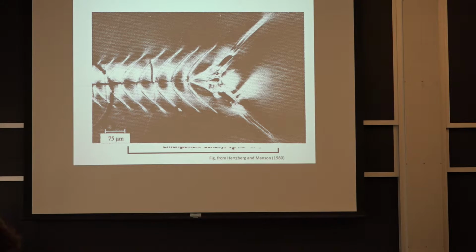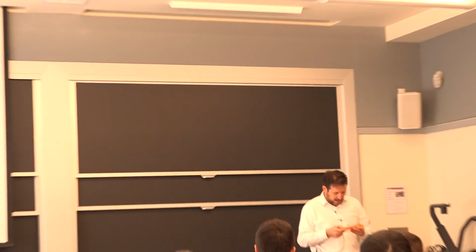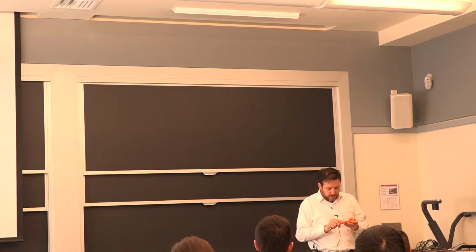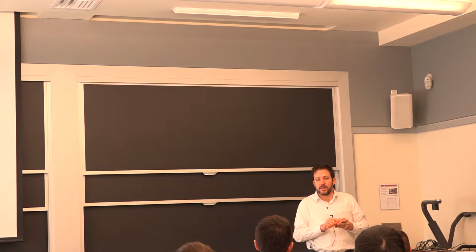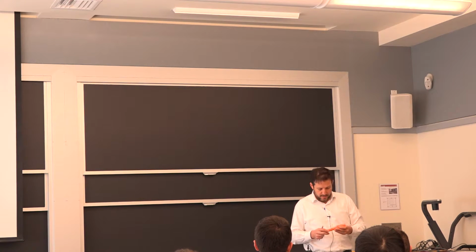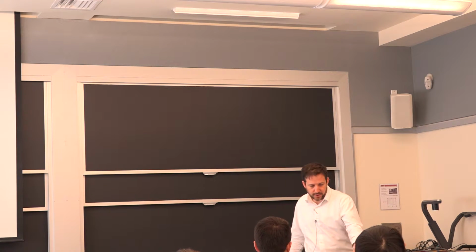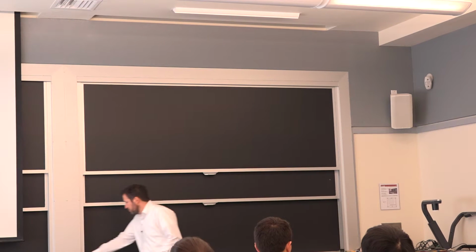So I do have a pipe sample here that I want to circulate around. It's cut in half, and you'll see one side is a clean cut that we did with a blade. The other side has a bunch of very slow cracks that started in service and grew all the way through the wall thickness before it failed. So I'll circulate it, and I'll sketch out a little bit what it says on the fracture surface.